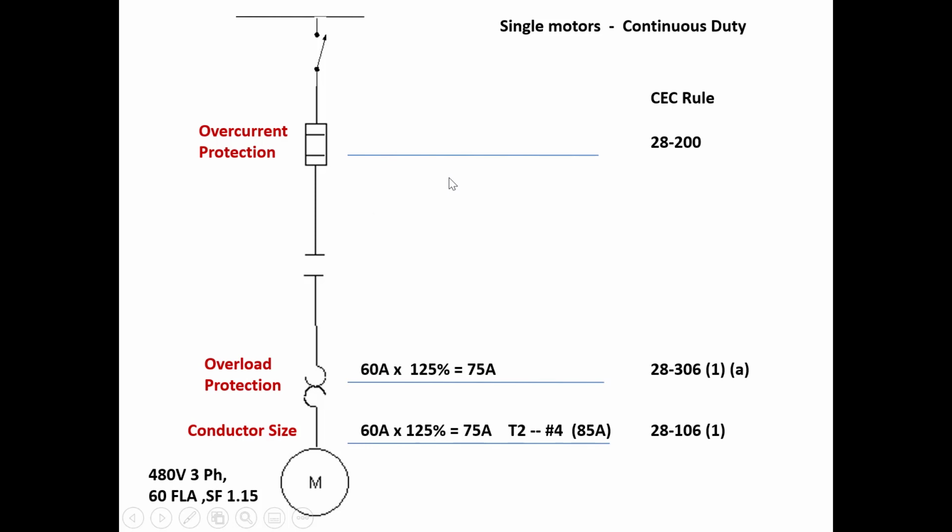Table 29 has a list of different types of motors. It starts with alternating current, single phase all types, squirrel cage, and synchronous. Under those it says full voltage, resistor, reactor starting. Full voltage just means basically no reduction in starting current. And then we have auto transformer start, delta starting, so those are reduced voltage, wound rotor, and direct current. So in this case we are a 3-phase motor, so we'd be a squirrel cage, full voltage, and we go to non-time delay, and it's at 300%.